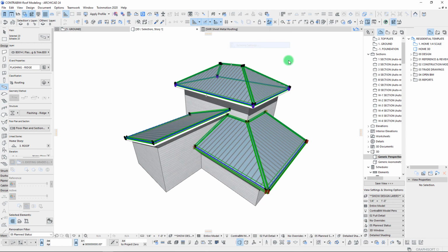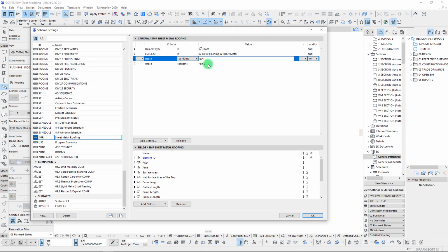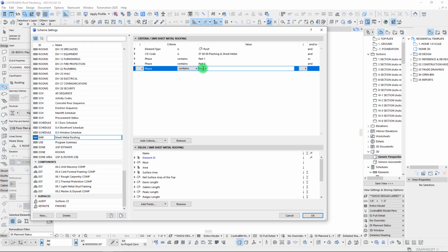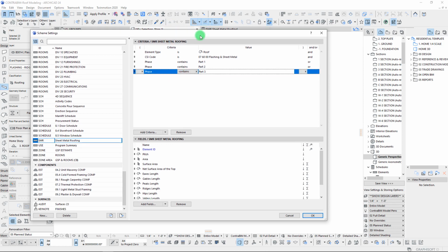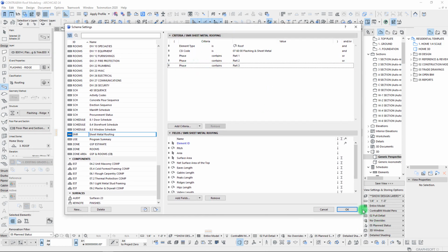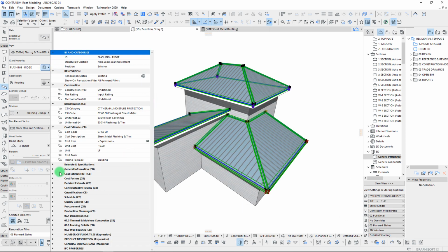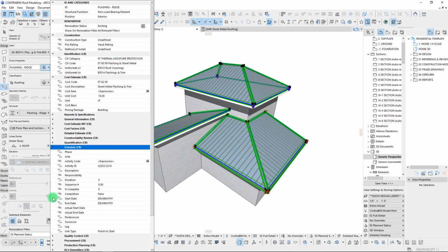But okay, so anyway, coming up next here, let's grab all of our beams. And just to do a quick recap of our takeoff, we had part 1, part 2. Let's add a part 3 here. Obviously, we could just continue to add them all based off just our single code here, but I like building these up like this, just to point out that we can set up these specific criterias for that purpose. And so now we're adding a part 3. We'll go through and highlight, or we already have all those beams highlighted. Let's get in here to our location where we have that criteria, which is in this case our schedule, and we'll add in part 3. I believe that's how I had it.